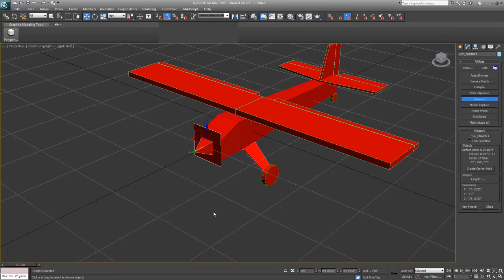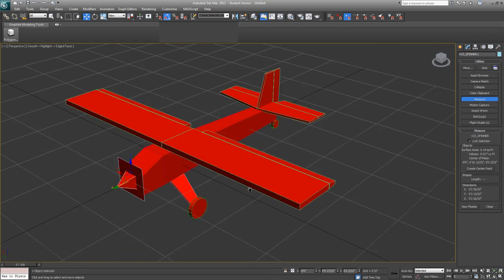I did have a propeller. That means that I named it correctly with this engine 1, which is pretty much the default for all KE aircraft. They're going to have engine 1 as the default name. But the names for the spinner and the engine need to match, and they don't. If I'm going to have a 1 at the end of engine, I need a 1 at the end of spinner. So I'm going to correct that. We're going to call that spinner 1.